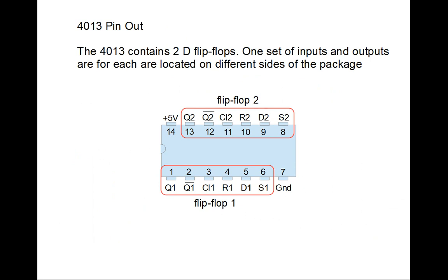Okay, this is the pinout of the flip-flop we're using. When you build these things, you need to look at this pinout. It's not particularly involved. The first thing to notice is you always have to put 5 volts here and you have to put ground here. Failure to do that means it won't work.